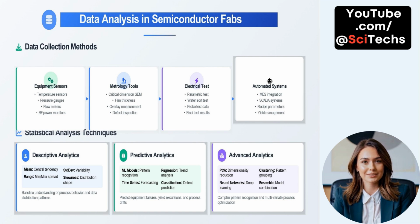Data analysis in semiconductor fabs. Data analysis in semiconductor fabs starts with structured data collection across 4 main sources. Equipment sensors track critical parameters like temperature, pressure, flow rates, and RF power to monitor tool performance. Metrology tools measure key features, such as critical dimensions using SEM, film thickness, overlay alignment, and defect locations, to ensure process control.